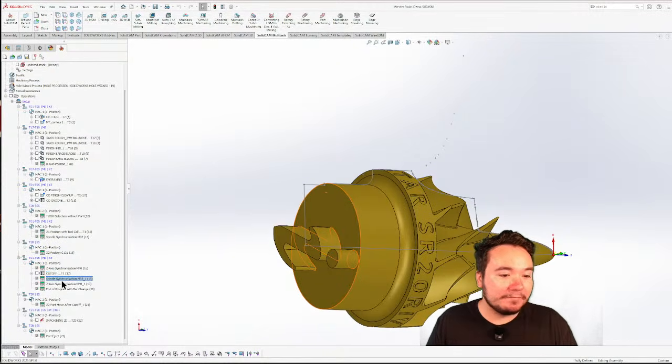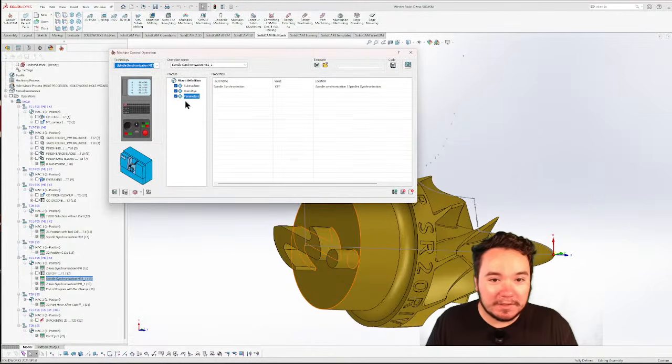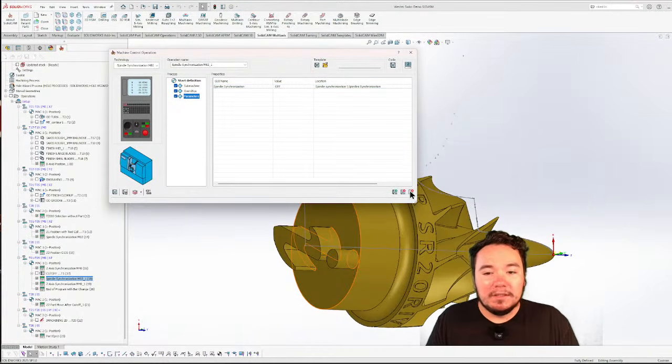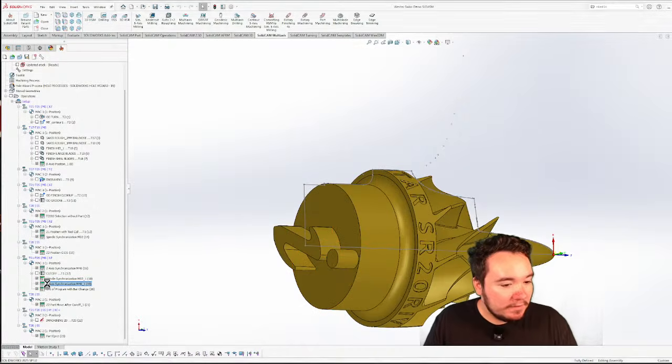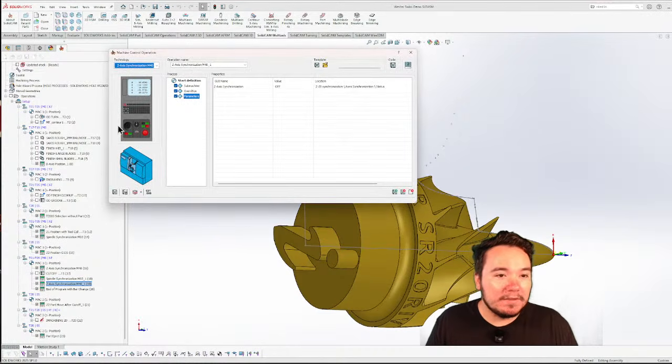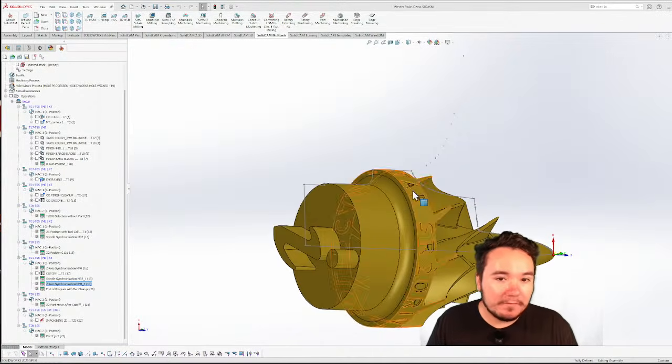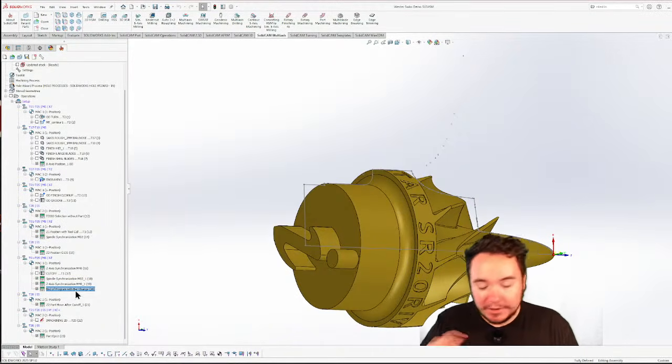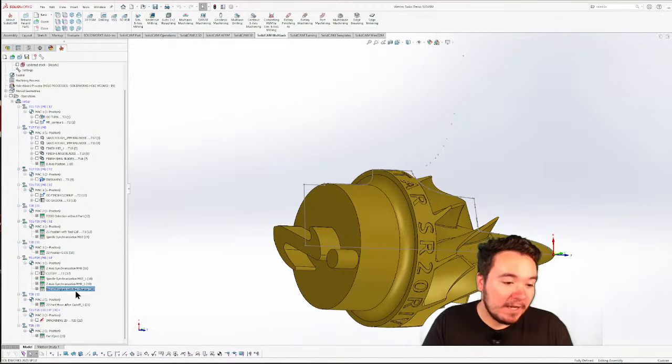Cutoff's done. Then you can cancel the spindle synchronization. You just turn the value to off. Exit. And then this is the Z synchronization, so you're just canceling both of them. And then you also put an end of program with bar change. You're telling the main spindle that, hey, we don't have a part there anymore. It's the end of the program.